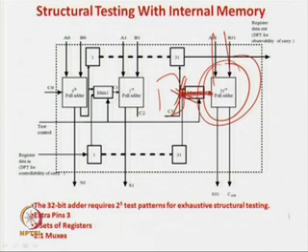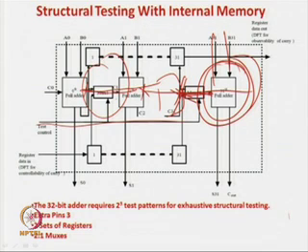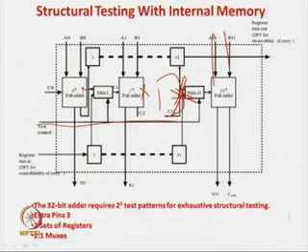So, the same philosophy, we apply our 2:1 multiplexer over here, and there is the test control. Whenever test control is, say, 0, the output of this feeds this, the output of this feeds this, and so forth. Whenever you are in the test mode, this one will be decoupled, this one will be decoupled, and you can have direct control of this carry through the multiplexer. So, in the test mode this is decoupled, and we can have direct control of this carry by this multiplexer.